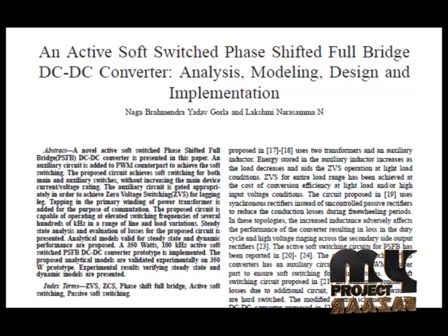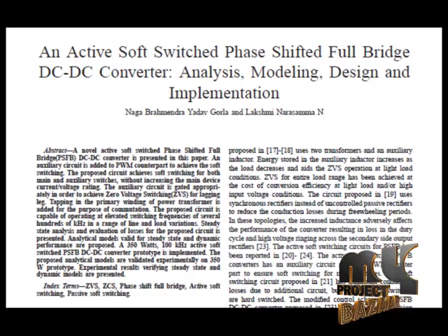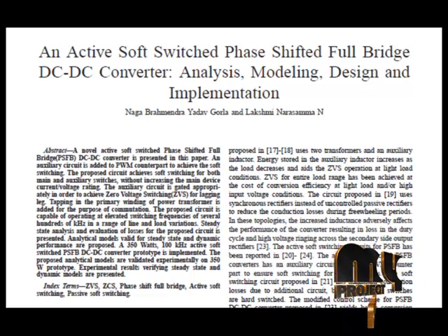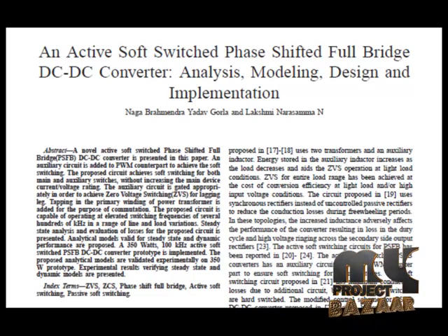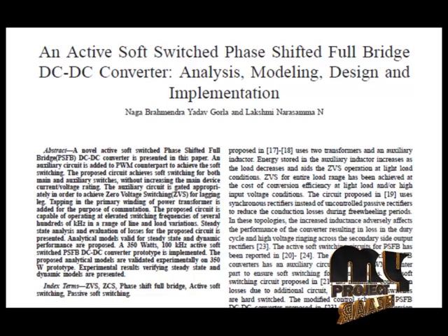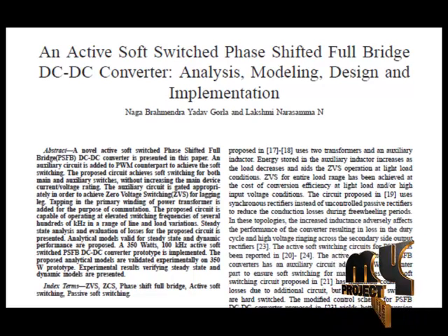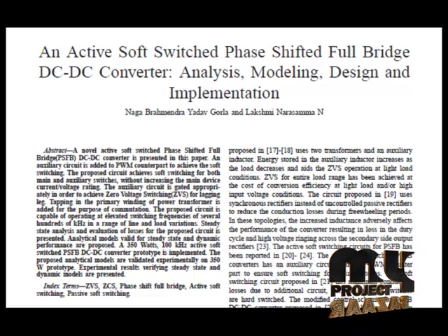Soft switch full bridge converters, such as ZVS PWM full bridge converters, address these issues. Salient features of the circuits proposed in these papers are a wide range of ZVS, complexities in implementation, and higher conduction loss during freewheeling intervals.